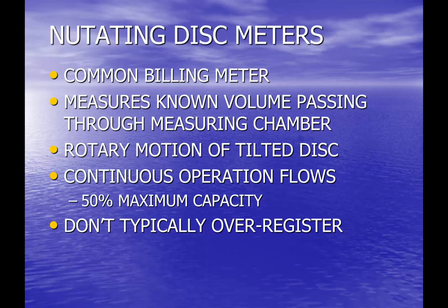But aside from just the sizing issue, as the meters get older, they tend to wear, and that's when they begin to under-register as well. So the challenge for water agencies is to look at when is the appropriate time to spend the money to actually replace a meter. And we'll talk about that when we get into O&M, about some ideas about when it makes sense to actually incur cost that ultimately you would recover as you are generating more revenue by a more accurate meter.